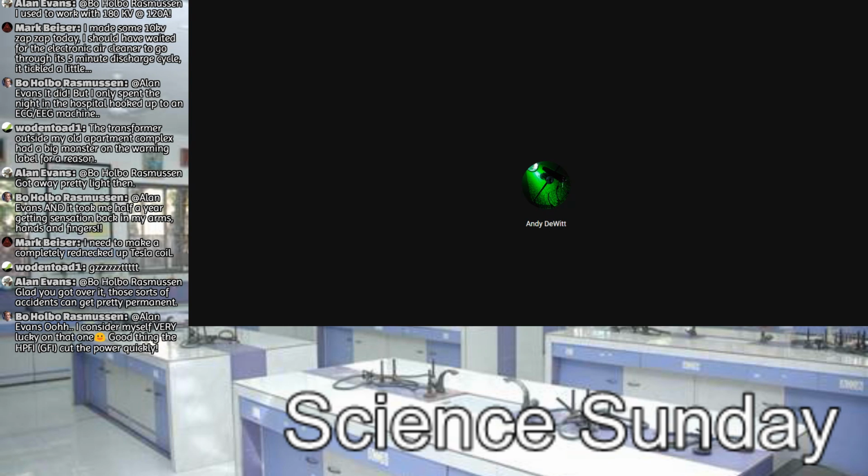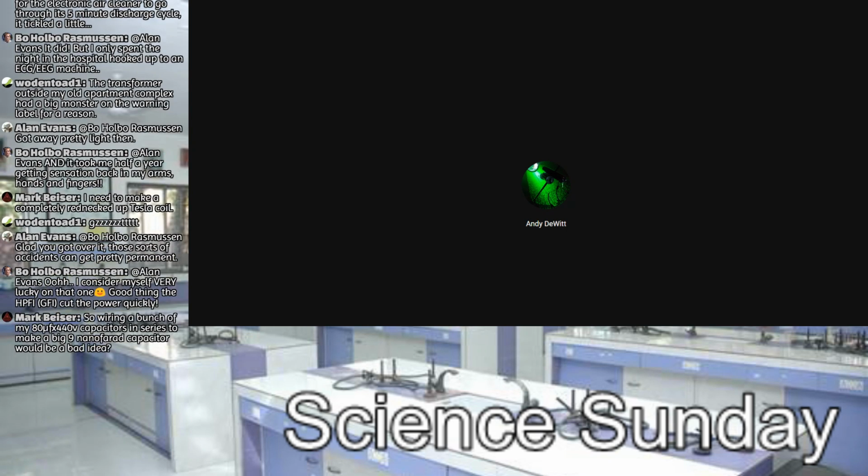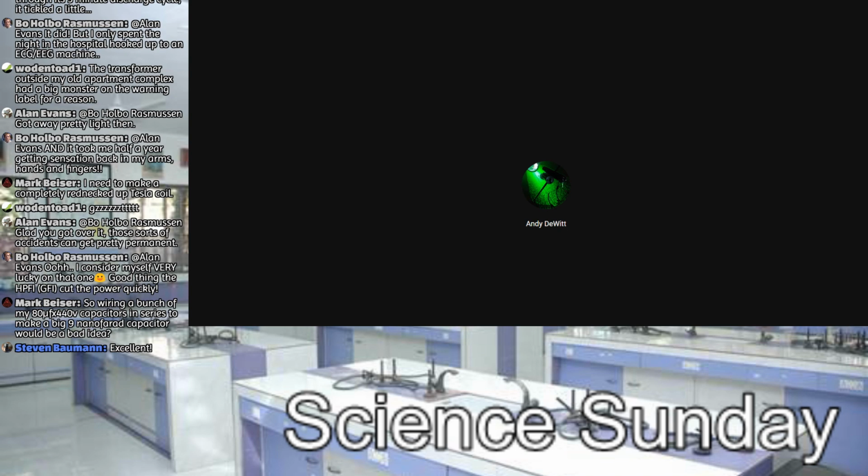What you're supposed to do is put a signal generator through a capacitor to the primary, and have the oscilloscope through a capacitor close to the secondary, and you're supposed to be able to track the pulses. You'll see the initial pulse from the signal generator on the primary energizing the coil, and then you'll see the resonant pulse like a wave very close to it. That way you can tune your coils so that the frequencies are very close. Now, you don't want them exactly on.